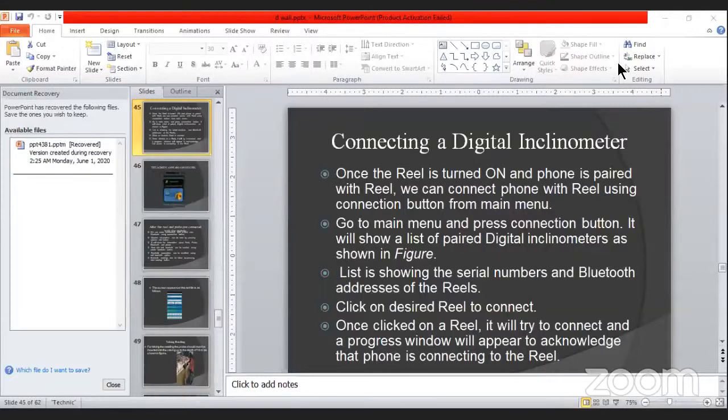The temperature of the concrete at pouring should be around the minimum temperature. The temperature should be 5 degrees Celsius to 32 degrees Celsius, and the slump which we are going to use is 150 to 200.